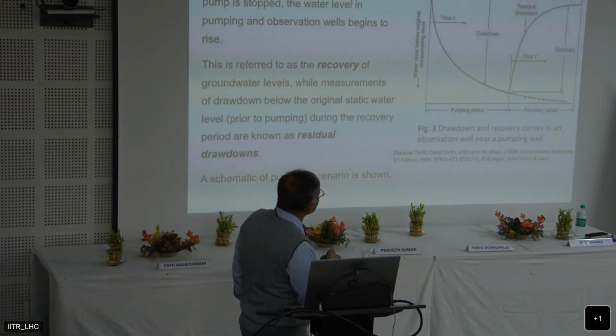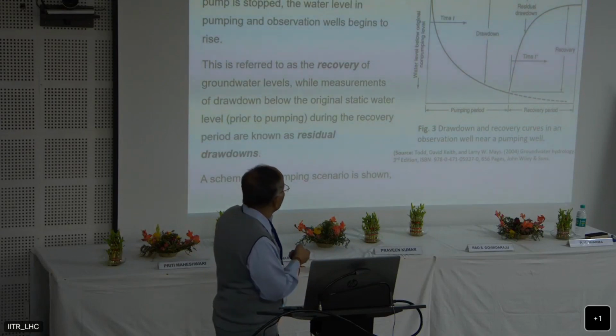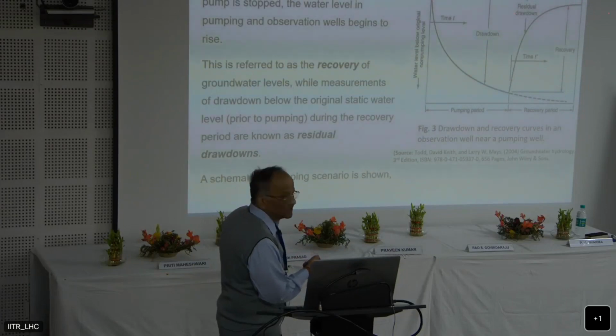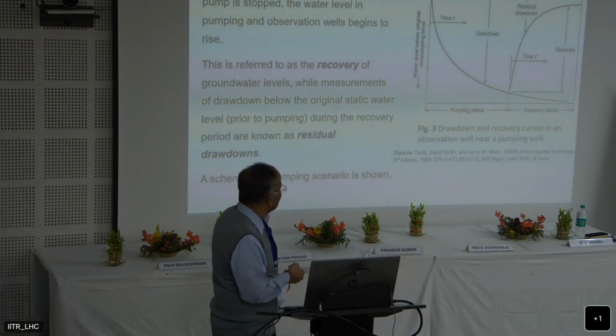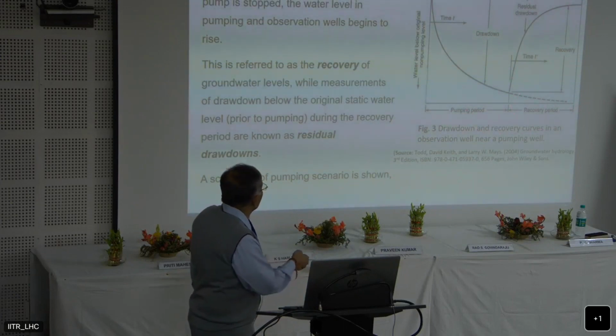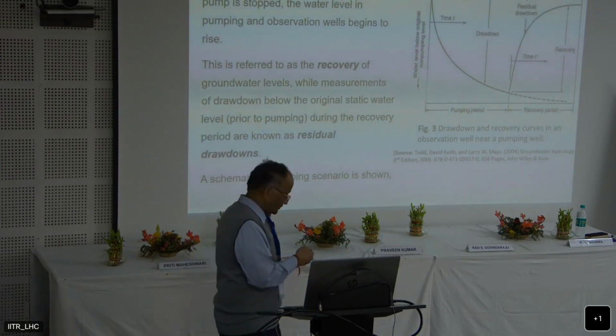So this is basically a typical residual. The build up during the recovery we call a residual drawdown. Let us say initially the drawdown is zero, and the piezometric level is here. Now it has come down up to here. When I stop pumping, it will again recover and reach the original piezometric level. The recovery period is considerably less as compared to the pumping period. The drawdowns or the buildups during the recovery, we call the residual drawdowns.